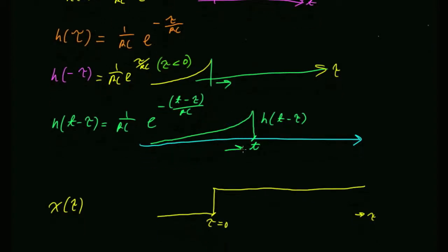So it didn't work for infinity because we had no signal at infinity. It was just 0. That's right. Then left t since t is positive, or no, because it's versus tau now. It's versus tau. So it's a right shift. It's a right shift because my independent variable is tau, and up here in the parentheses I've negated it. So because it's negative, everything's opposite.